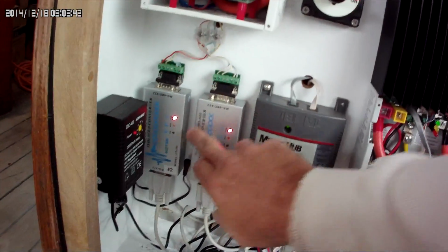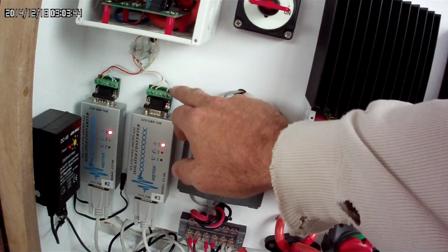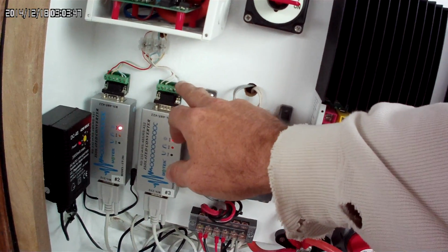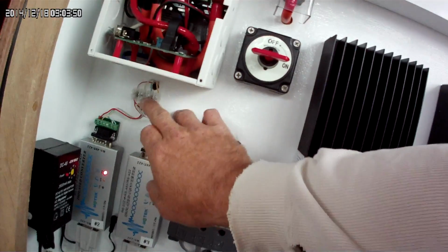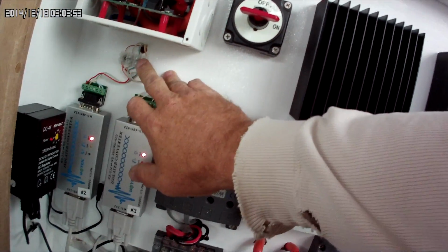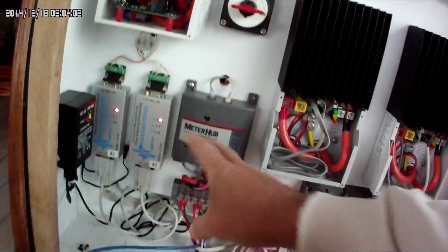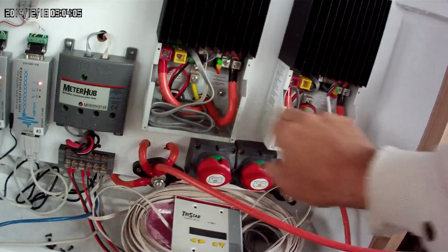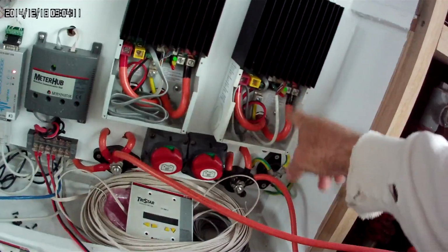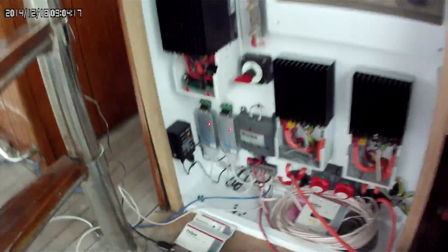So I have no TX Lite. I've got my TX Plus and TX Minus. All goes up to my connectors here, that goes into the controller, to the RS485. But right now I have no communication between this serial and this serial port right here. I have left this connected, and I ran it through those new cables that I showed you, the new serial to USB. They're straight through cables, so they should work, and they do work.